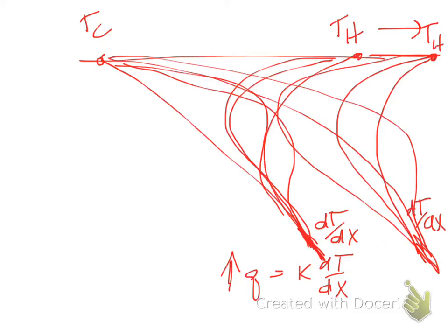Either can work, you just have to be aware of how the difference in that bottom boundary condition will affect your ultimate solution. If your bottom boundary condition is 100 kilometers away, then it might not matter which one you choose. If you're only interested in the top 100 meters and you put your boundary condition way, way far away, then you're not going to notice the difference in the two boundary conditions. But if your boundary condition is close enough to the area of your interest, then you will get a different answer if you put a different boundary condition on it. Does that make sense?